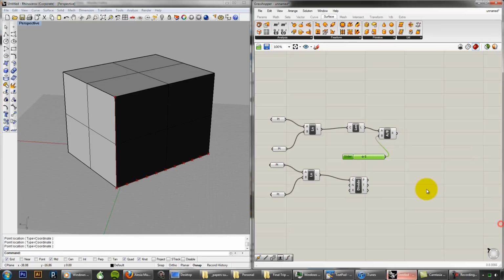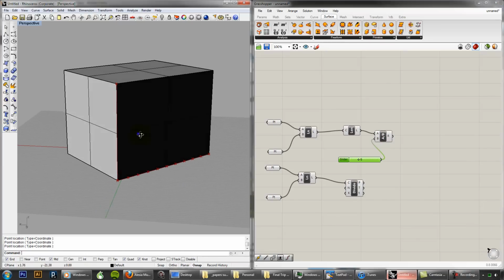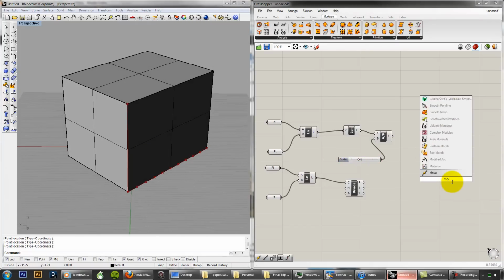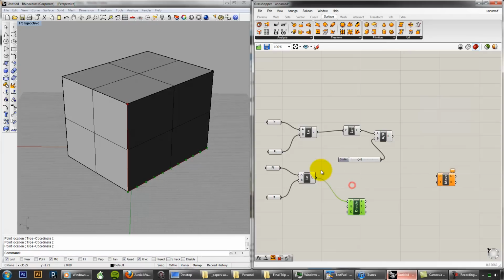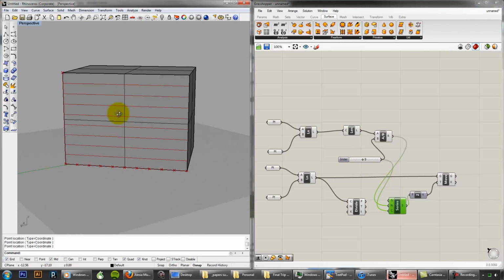And the benefit of that is that this allows me to do things like moving a line in the Z a specific amount. So if I make a series, and if I know that this is the distance between each one, I can plug that in for n, and I plug in c as the amount, and then I actually get, so if I want to divide this up, so that's nice and parametric.